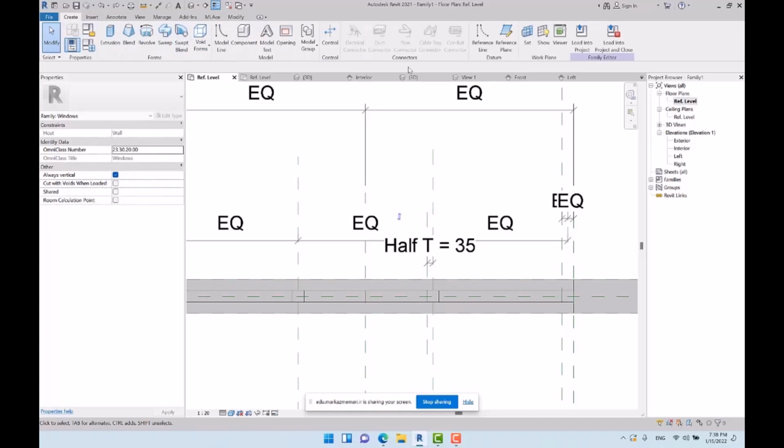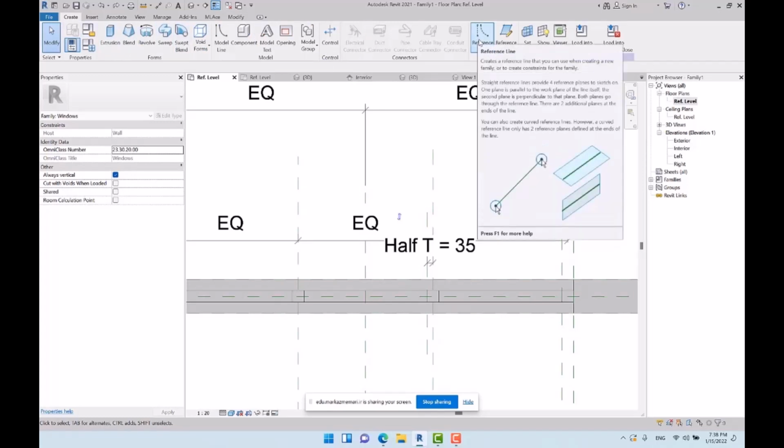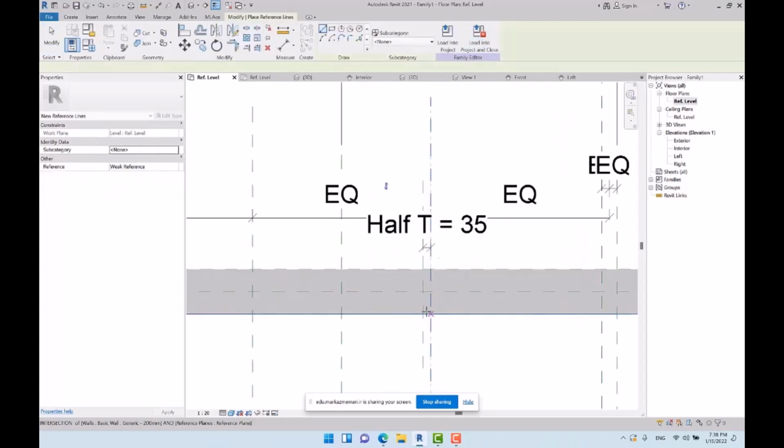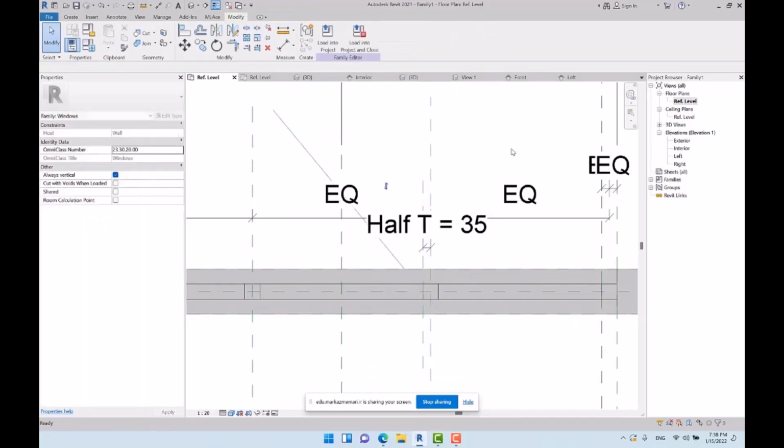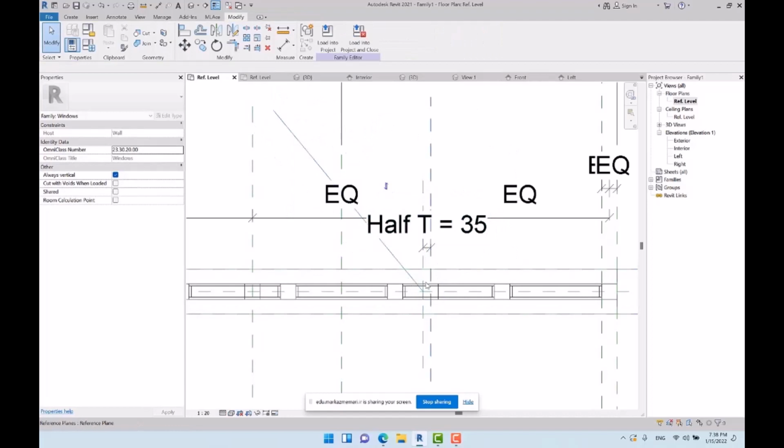This time I'm gonna work on the angle. So here in create tab, I pick reference line. As you can see, I select reference line to sketch it. Exactly, I sketch it from the intersection between these 2 reference planes that are crossing each other. And I want you to note that all of these stages that I'm gonna pass are vital to be done.